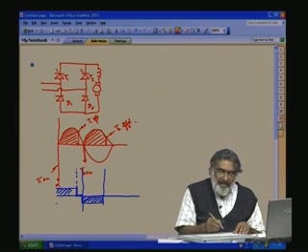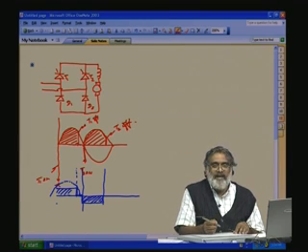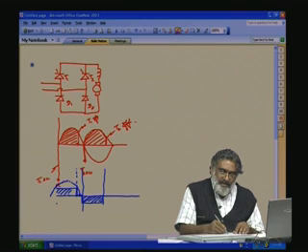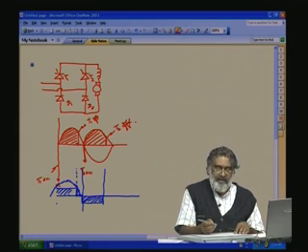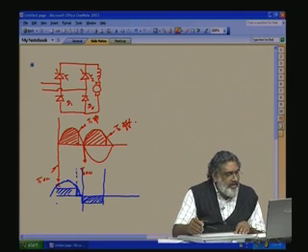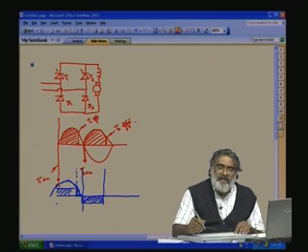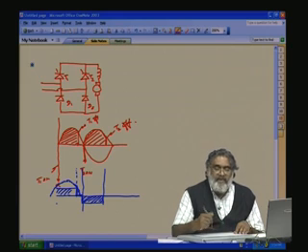So, if you see here the fundamental, if this is the fundamental voltage, the fundamental current is leading the mains voltage. By this type of application where the current is leading, we can use it in compensation for line voltage drops. Suppose in the line, a large inductance is there, so an L omega drop is there. By giving a leading current, we can compensate that line drop.